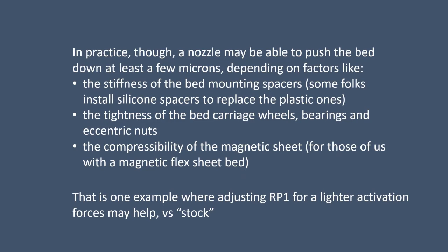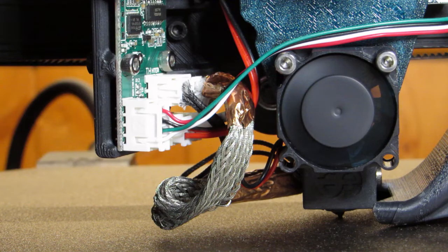So the diving board bends up, the strain gauge says, hey, we've hit something, and the machine says, oh, that is the bed. But by then it's already deflected the diving board up. So at that point, Z axes are already below the level of the bed, and it needs to release that strain to be back up at 0.